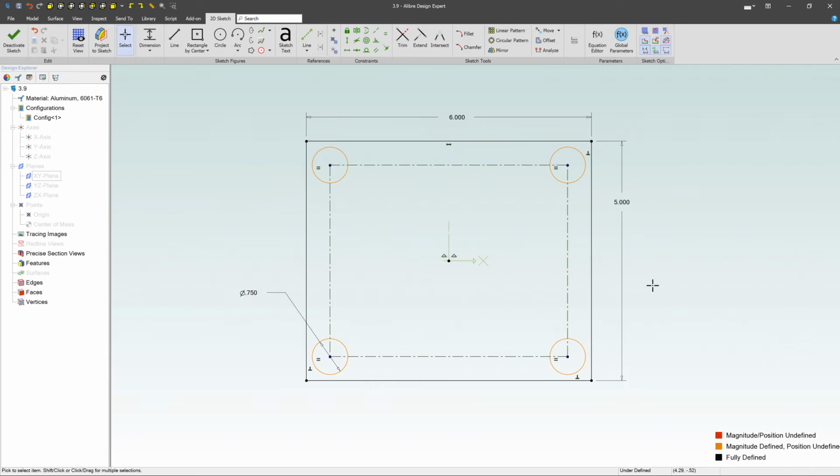Now, think about how much work that would be if you didn't have this rectangle on the inside. Right? You'd have to add some dimensions between each line, and you can still define this, right? You can keep adding dimensions here, and that's just fine because it's already been offset a 1/2 inch, but it allows you to quickly offset all those lines and eliminate all those dimensions you would have probably had to do before. And you can use offsets for a lot of different things.